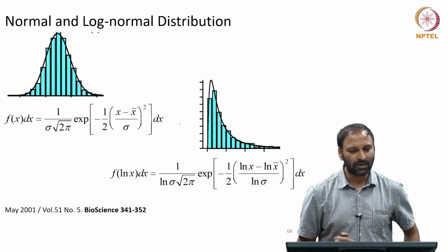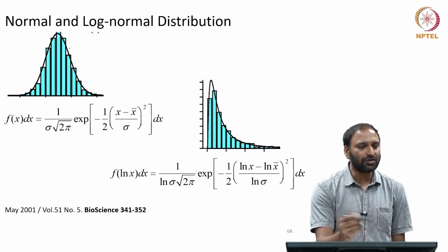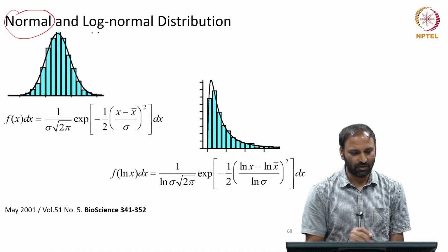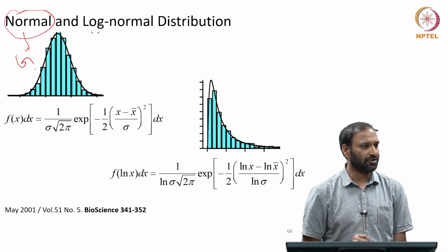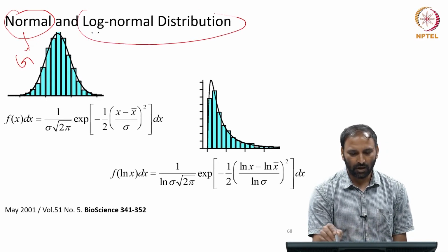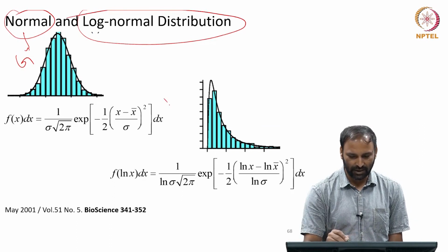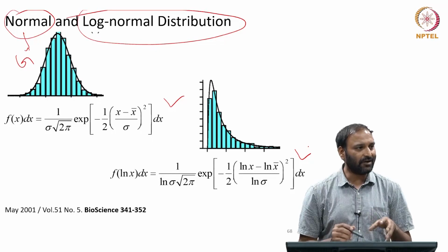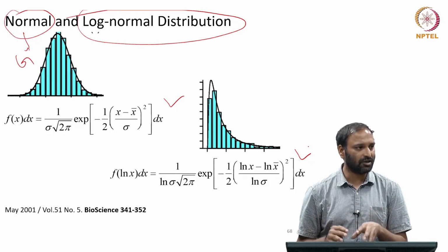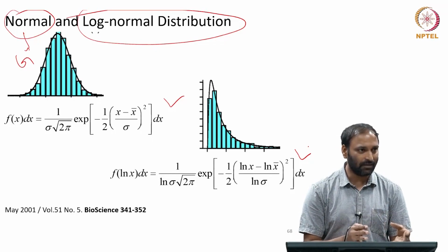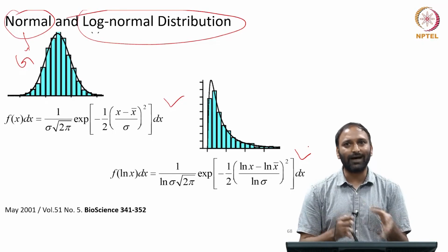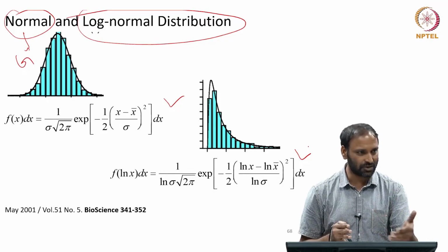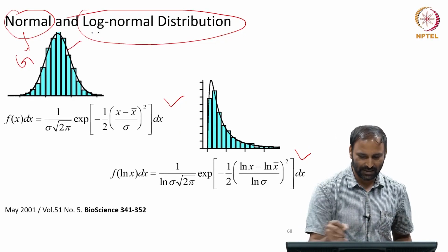So, what people do is you can actually use some continuous distribution function, something called a normal distribution function. It is also called a Gaussian distribution function, or what is called a log normal distribution function, which are represented respectively by these three expressions. Then I can fit these known distribution functions to the discrete data that you have obtained, and the more classes that you have, the closer your discrete representation would be to the continuous representation that is represented by these lines.